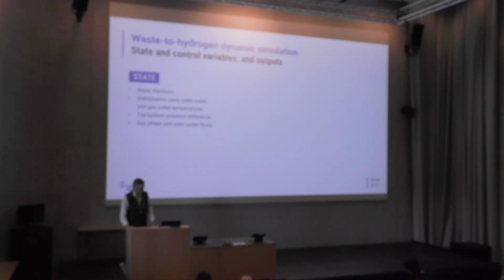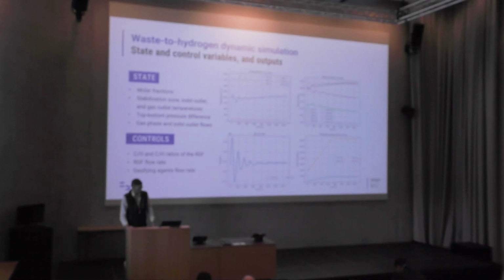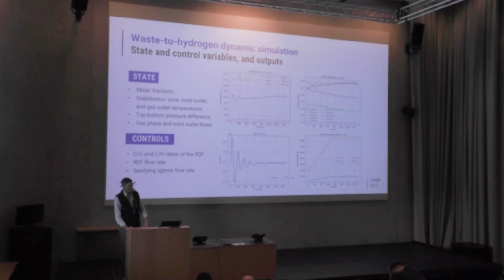So we wanted to be able to predict the state of this system, molar fractions, temperatures, pressure drops, and we wanted also to be able to inject some controls into the FMU, like the ratios that characterize the solid inlet and the inlet flows of gasifying agents and solid parts. This is very briefly what the machine learning model was doing.